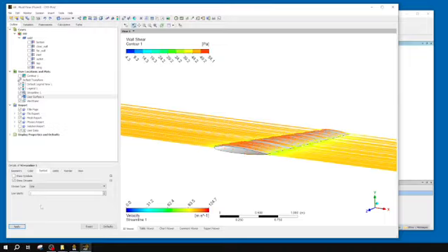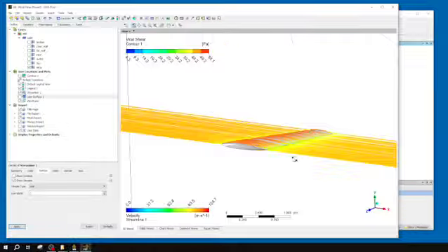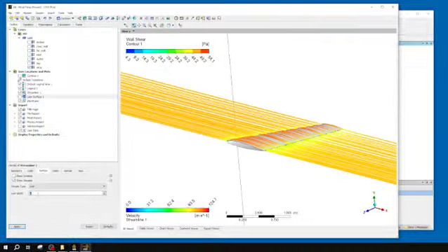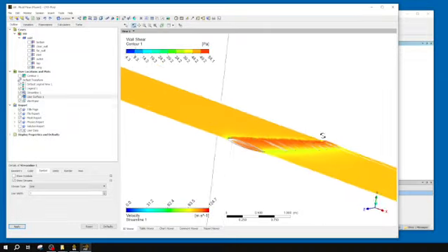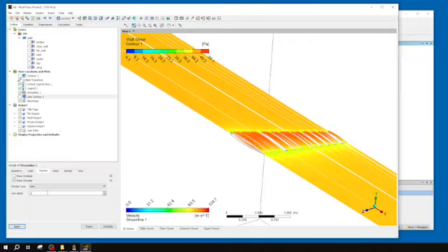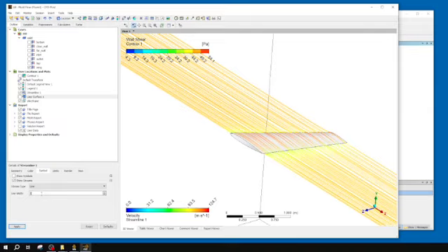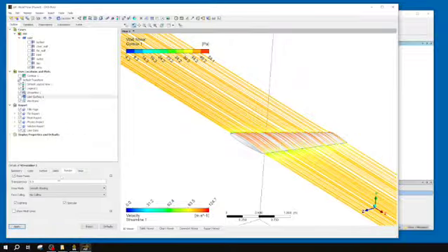The bigger thing we'd want to play with is what our line is. So you have 3 options: line, tube, and ribbon. So this line is, as implied, just a line. You only can change the line width, right? I can make it thin and kind of wispy, or I can make it very thick and fat, right? So those are rather thick lines, and they're pretty dark. I'll go back to 2 actually. One unfortunate thing about using lines is you can't use a line and transparency, so I'm going to make it 0.7, and you can see nothing changed.